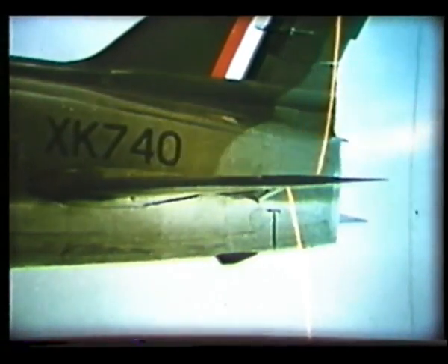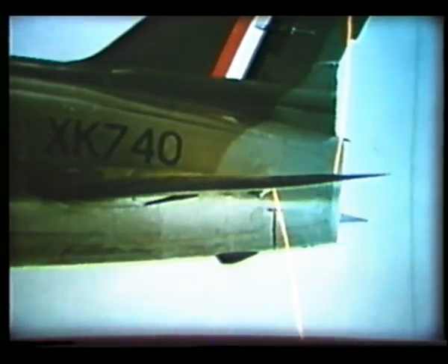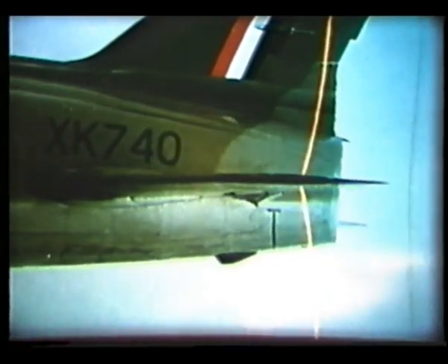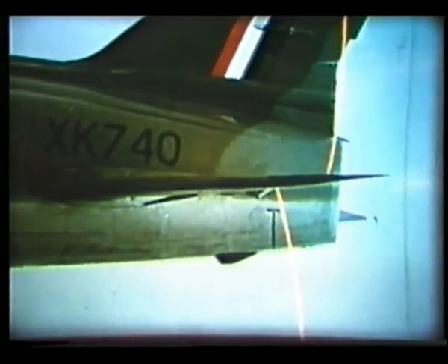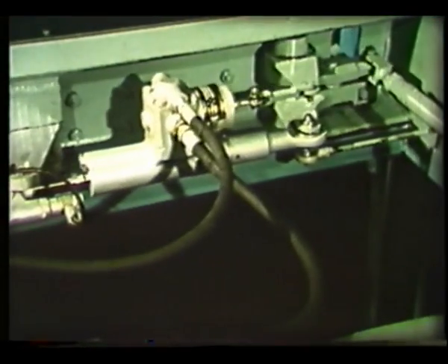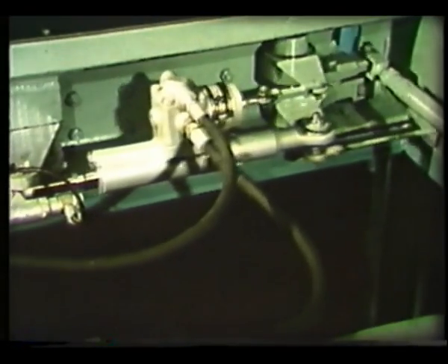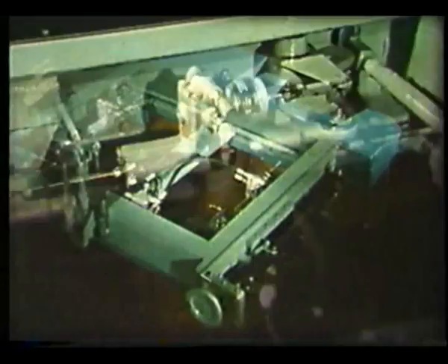Such moving tailplanes can give up and down trim control with much smaller deflection than the elevators on fixed tailplanes. For proper control at transonic speeds, powered controls are almost essential to overcome the huge forces on the control surfaces.